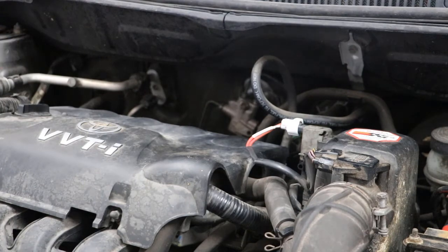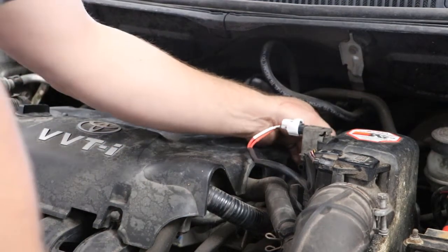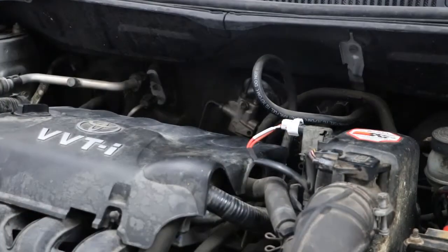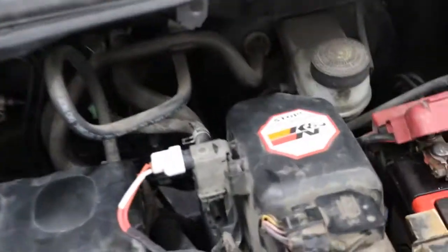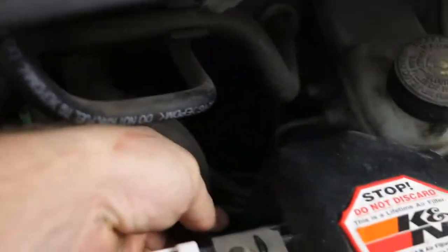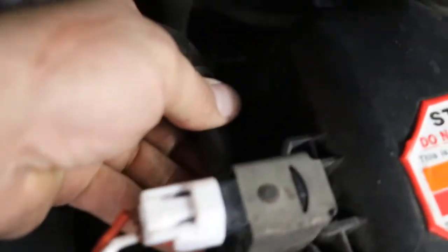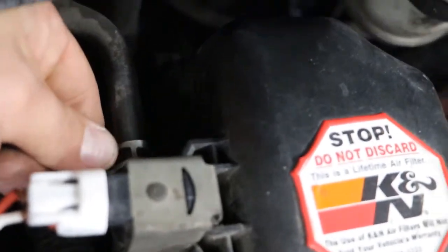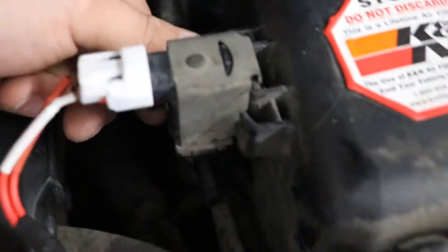So the next thing we need to do is reconnect the hose on the back of the solenoid. This one went back to the gas tank. We kind of tested it. So we're going to slide this piece right back on here. On the back of the solenoid, it's hard to see. So right here. And then you do need to pinch this clamp, move it up, and make sure it seals well.